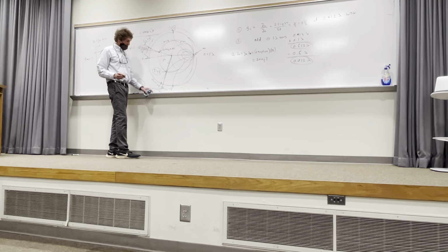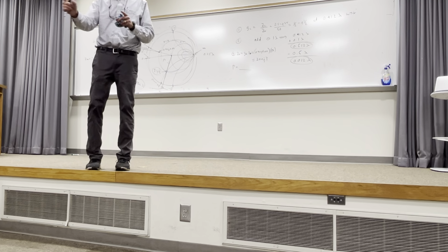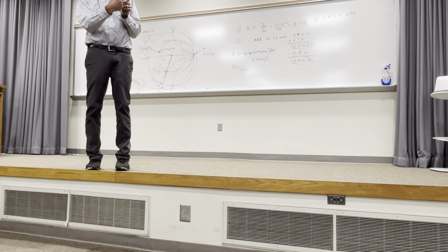Negative 116, 17. Well, I mean magnitude. You need to take that and measure it. You need to take your compass or your straight edge, measure that distance, then take it down to the bottom of the Smith chart, the very bottom. You all see how you can get SWR on the very bottom? It's a measurement. You're gonna see a couple of things. It'll say either VSWR or SWR. Y'all see it?